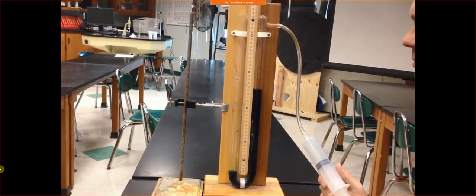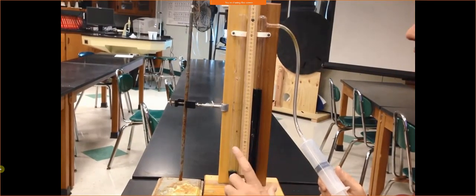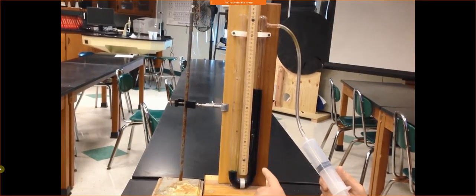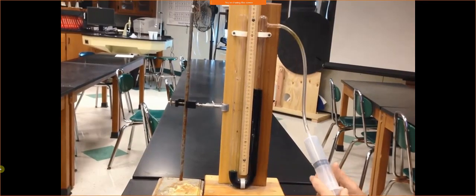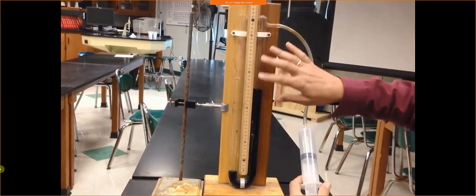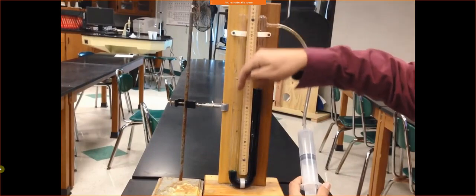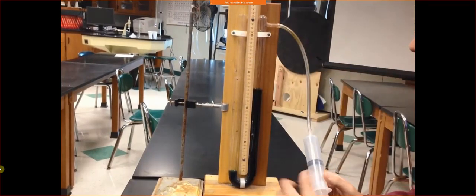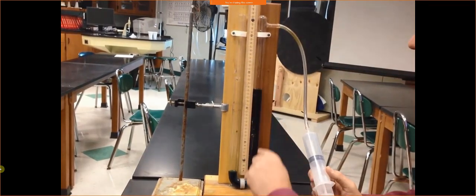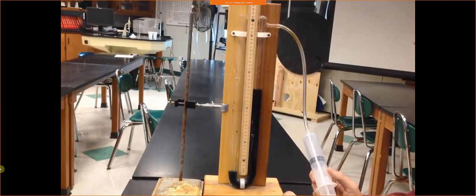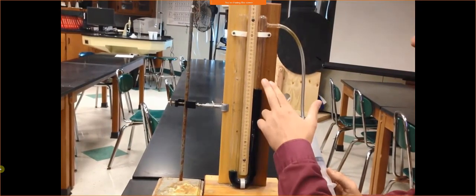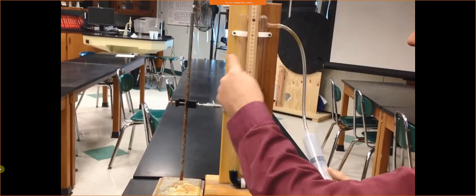So we would do 760 minus 190, and that would be the pressure here. So this pressure here is lower. Clearly you can see the atmospheric pressure is winning by 190 millimeters of mercury. And again, the pressure in here is 760 minus 190.